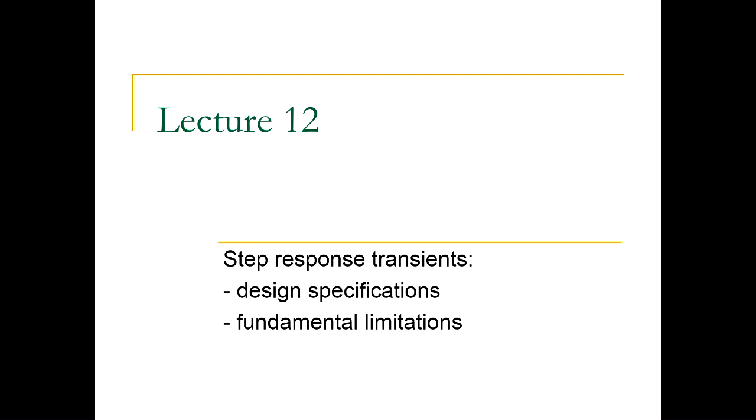Not feeling great. Last week, Guizhou talked about steady-state errors, and he introduced sensitivity transfer functions. So sensitivity transfer functions are very useful beyond steady-state errors. But steady-state errors was one outcome. You could see that you can easily write some useful formulas for calculating steady-state errors via the sensitivity transfer functions. Now, in today's lecture, I want to go further and talk about transient response.